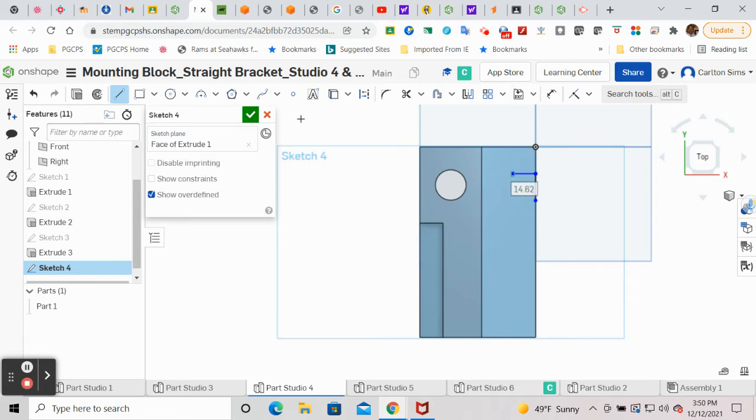And from there, I want to grab my arc. I'm going to use a tangent arc. Okay, so I'm going to select tangent arc. I'm going to go right back to the end point of that line and click. I'm going to bring my arc and reference that point there. When I get here, it'll give me the yellow guidelines, as you can see, so I'll know where to click to keep that even.